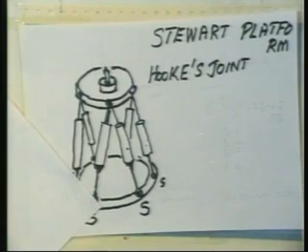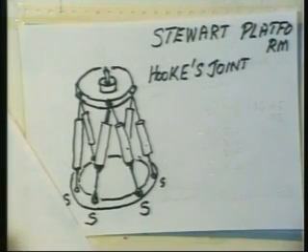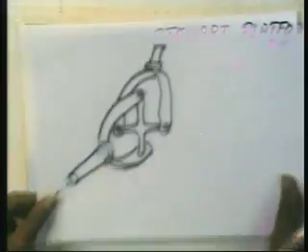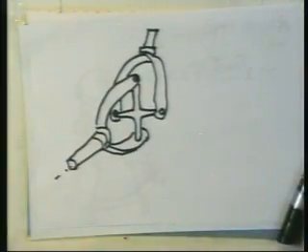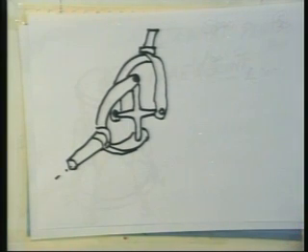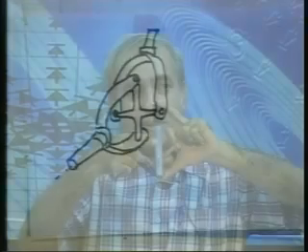It's a 2 degree of freedom joint. Here I have got a picture of the Hooke's joint. The star like thing, you know, 4 across, you have a cross, and one side of the cross you hold like this, the other side of the cross.